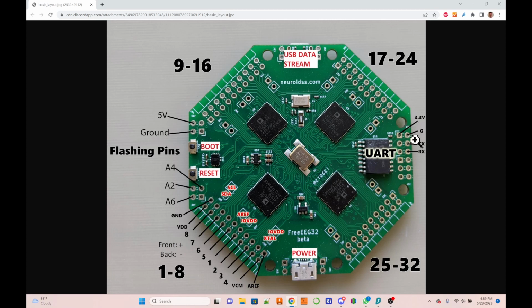I believe though that this needs to be powered, and maybe this thing is 3.3 volt capable, but I myself use these ports here, and this thing needs to be powered with 5 volts, and so I actually have an additional little wire that I solder from the power supply, which is 5 volts, to power this system here, because this here is isolated from the rest of the board. But only do stuff here if you really know what you're doing.